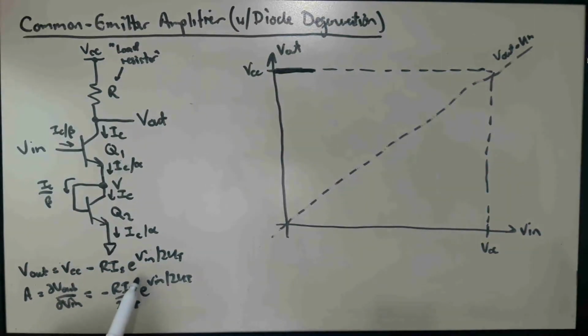Meanwhile, this current, as we increase Vn, is exponentially rising. Okay, it's not rising at a rate of 60 millivolts per decade, but it's rising at half that slope, and so it's going to be 120 millivolts per decade. But after a few 120 millivolt increases in the voltage, this current will very rapidly approach a milliamp.